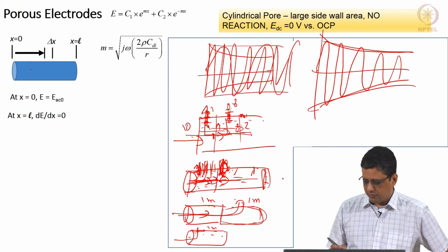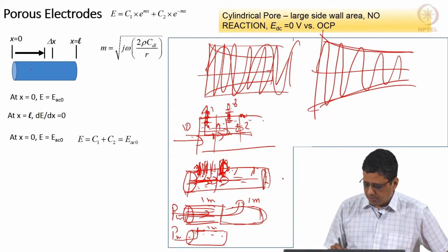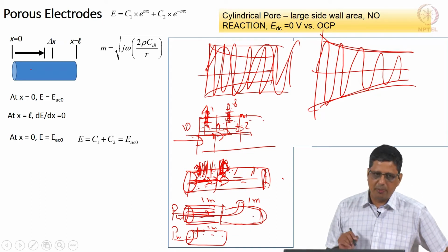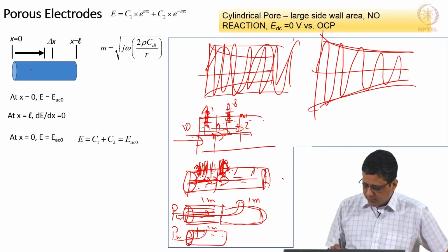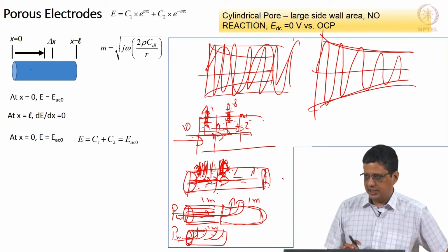Does it make sense? Same pressure in, this will offer a pressure drop. As long as there is a flow, there is going to be pressure drop. This will cause a lower flow rate compared to the same P in with no initial section.